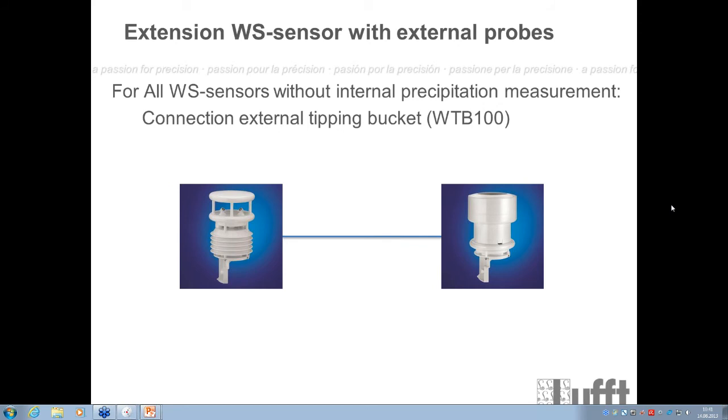And within the first 5 seconds, you will be able to connect with the UMB Config Tool. If you connect with the UMB Config Tool within those first 5 seconds, then the sensor will stay for 10 minutes in standard. And every time you send a command with the UMB Config Tool, it will again be extended to 10 minutes. And in this mode, you will be able to change the configuration again. That's how it works.